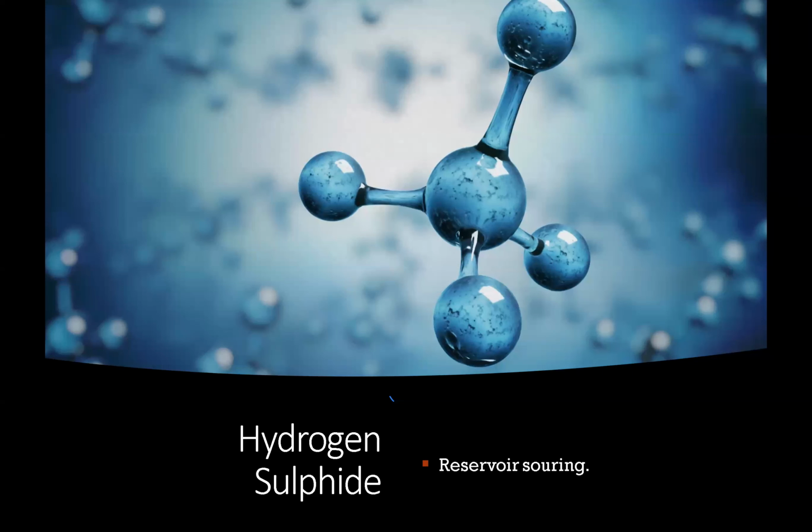Okay. So Ahmed is asking, what is the way to get rid of wax in the pipeline? One of the ways they use is pigging to remove this wax from the pipelines. So running these pigs inside it and remove all that. Or yeah, they use heaters for certain spaces for the wax deposition.